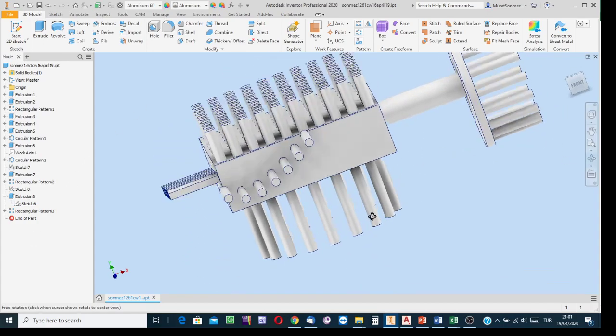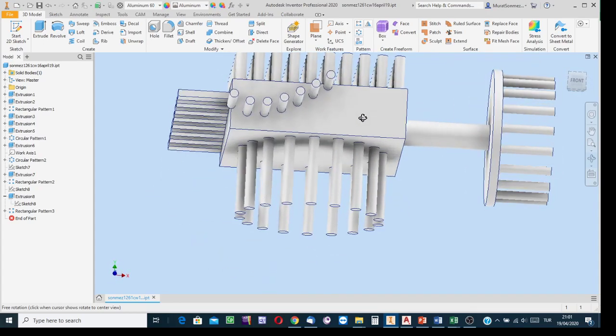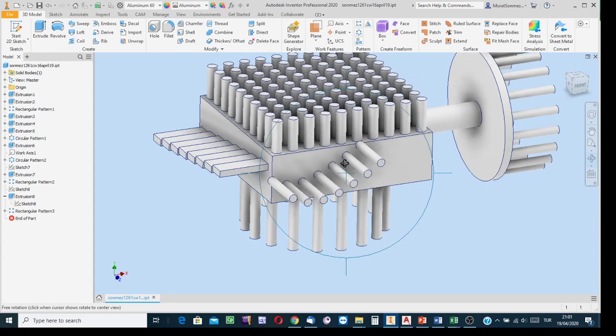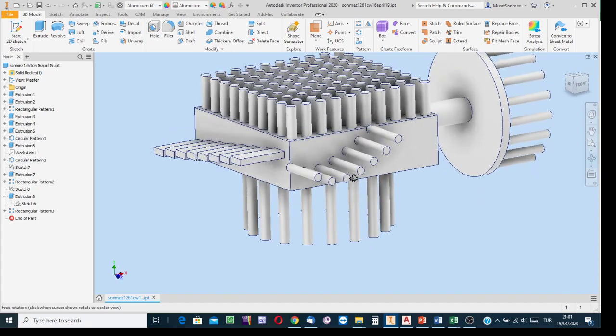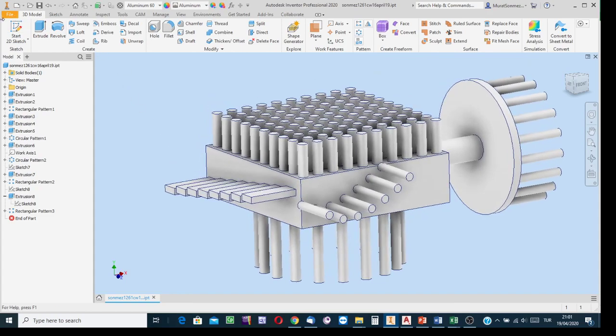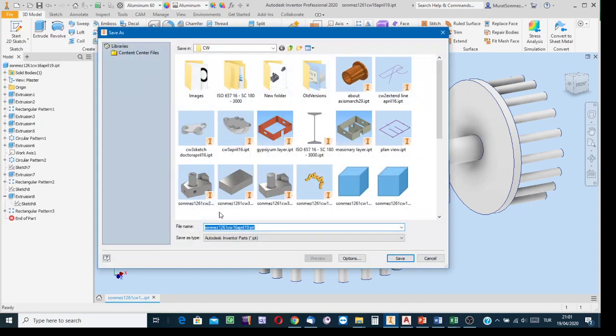Yes, dear students, I think it's okay. I educated you on how Excel data can be imported to Inventor. And then there is one more time an array copy process, path array. Here the path for this array is a straight line, but that one is a spline. And for having the path here, I used the Excel file. Okay. Save this file, saying in other classwork, save as classwork 20.